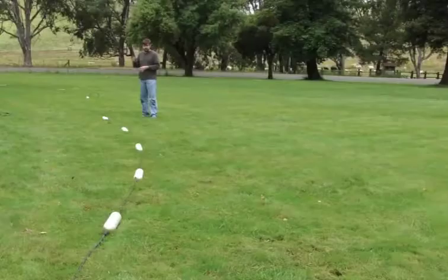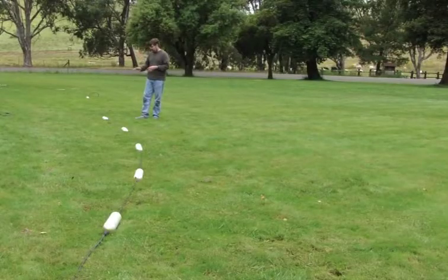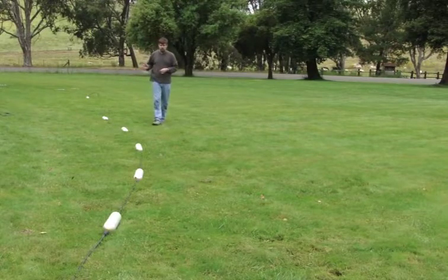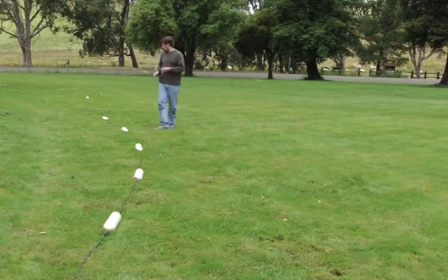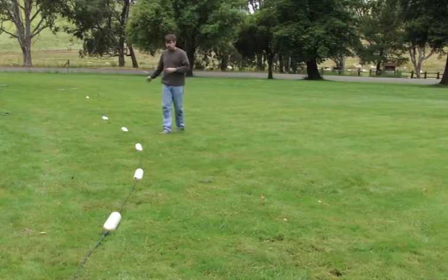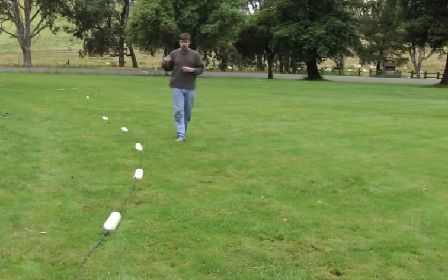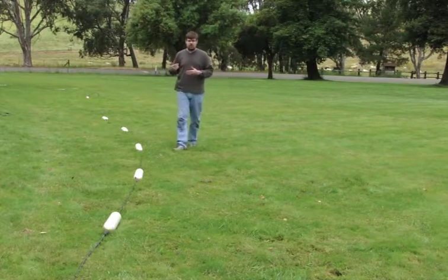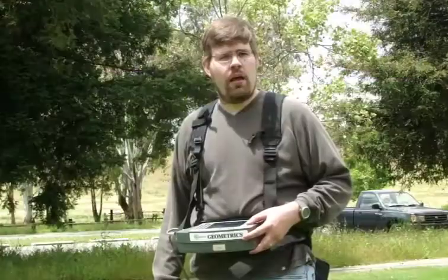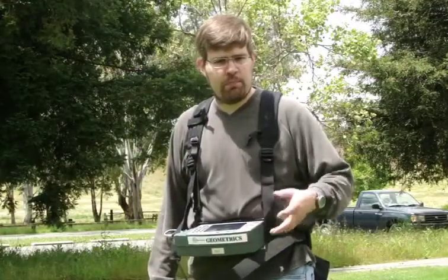Here's how it works. A transmitter electrifies 2 coaxial cables, transmitter dipoles, with an AC current. Current is then coupled to the earth through the capacitance of the cable. A matched receiver, automatically tuned to the transmitter frequency, measures the associated voltage picked up on the receiver's dipole cables. The receiver then transmits a voltage measurement, normalized to current, to the logging console.